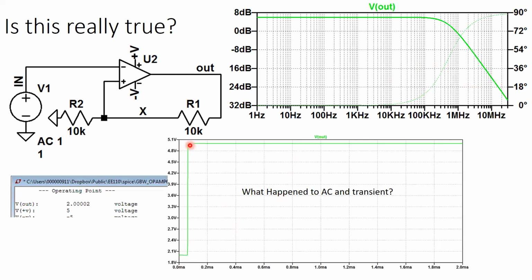All right, this is not working, right? Because if I put in 1 volt, I should get 2 volts out. Now I'm getting 5, and it's almost as if it's exponentially going to that. Look at the phase. 0, 0, 0, plus 90. That's positive feedback, right? So this is not a low pass filter because the phase is going from 0 to 90, right? What I have here is that if I properly modeled it, I would have